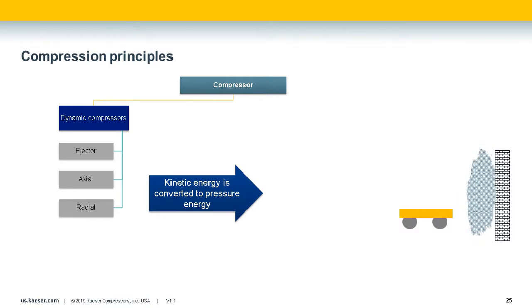But for these dynamic machines, the acceleration of air molecules generates what we call kinetic energy. The blower transforms these high velocities into another form of energy known as pressure. This happens through the acceleration of the air into a diffuser to allow a low flow speed, widening across the section of the pipe of the compressor and the impeller. The kinetic energy is thus reduced, resulting in an increased pressure as a result of conservation of energy. Okay, let's go to the next slide.